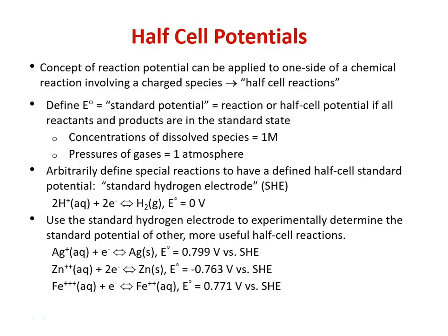And if we look at two dissolved species, which we can frequently encounter in corrosion of steels, ferric ions to ferrous ions, Fe3+ to Fe2+, if we're going to reduce Fe3+ to Fe2+ by adding an electron to that ion in solution and getting another solution ion, that occurs at a potential right around the same potential we would have to reduce silver ions to silver metal. Coincidentally, they're not related per se, but that's 0.771 volts versus SHE, our standard hydrogen electrode.